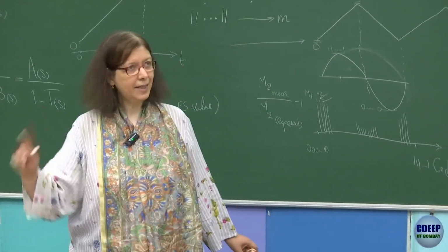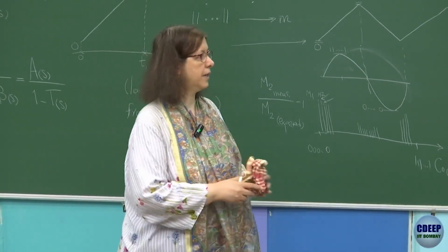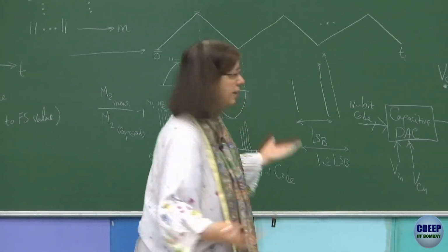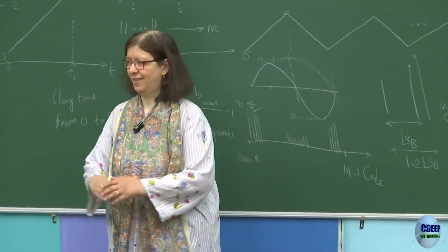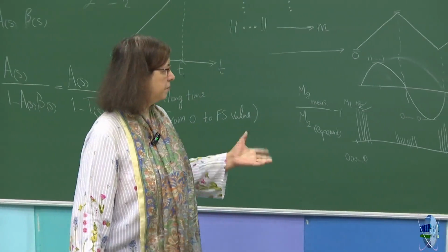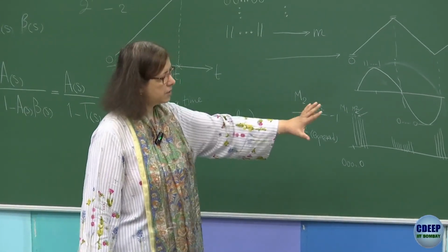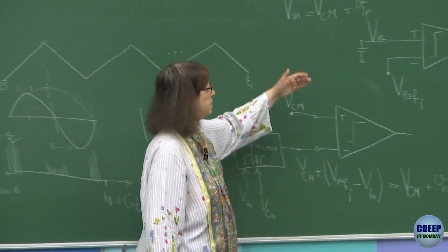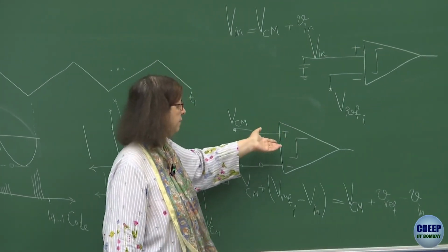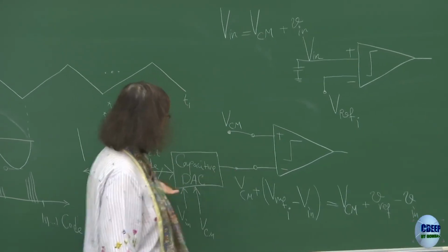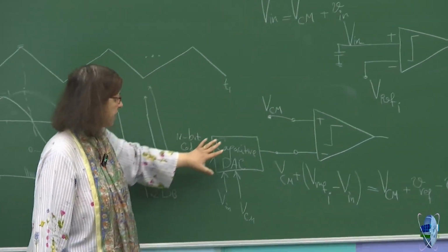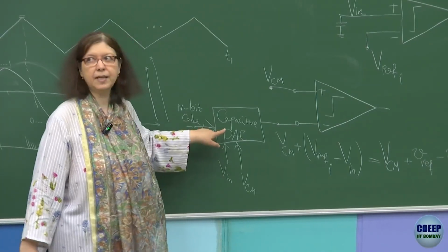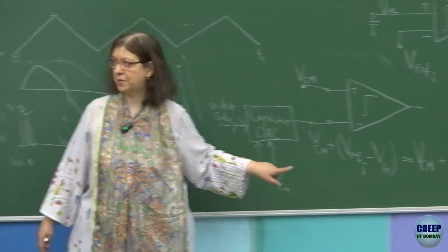And in the other case, when we use differential mode and common mode in differential architectures, when you use differential mode, naturally it is like a small signal. Anyway, this is actually the concept. First of all, why do we need a separate Vin and separate Vref? We put them all in one capacitive DAC. However, the capacitive DAC plays two roles. For Vin, it is like a track and hold circuit.